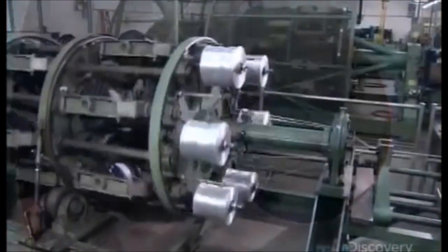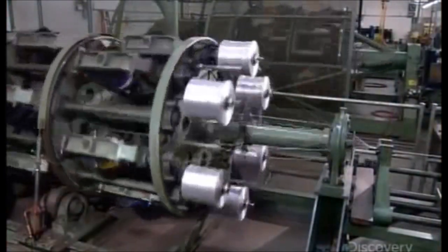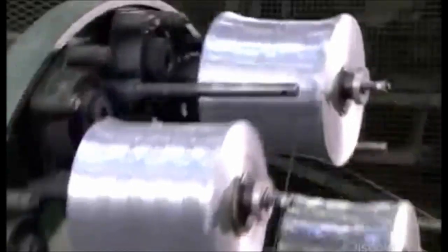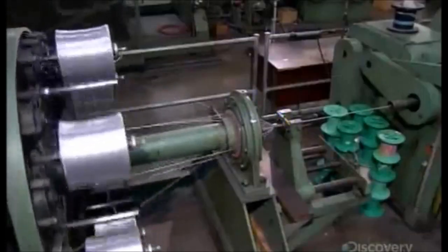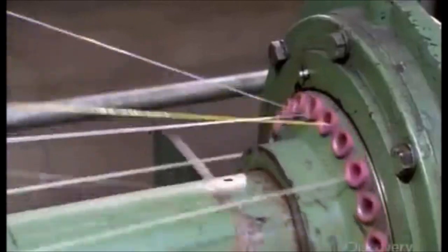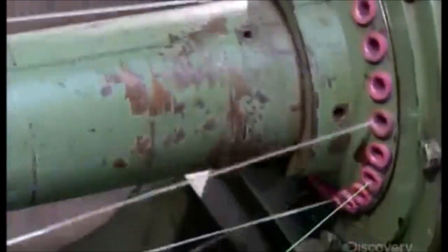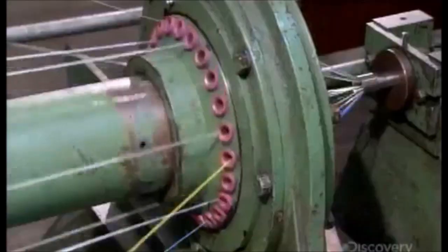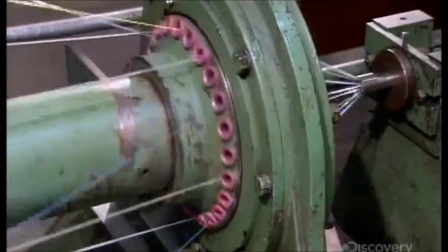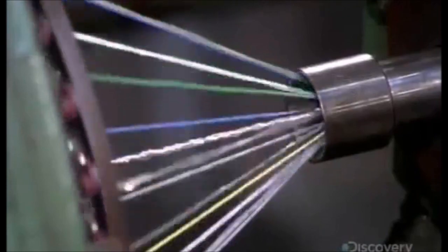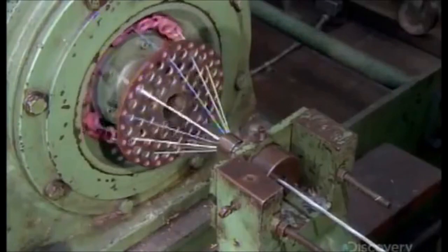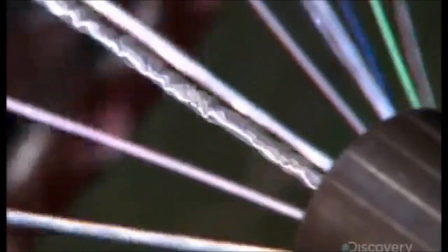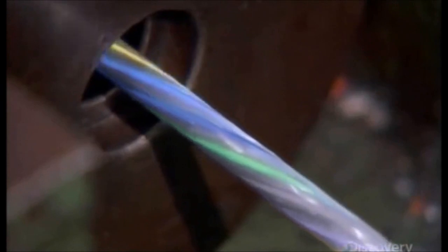At the center of this particular cable is a twisted pair of insulated conductors. Around them go color-coded insulated conductors and fillers to fill in the gaps between the conductors, giving the cable a smooth cylindrical shape. Here, the fillers are strands of polypropylene foam. An orientation plate aligns the components in the proper configuration as they enter the cable assembly die. The components exit the die with the fillers wound around the insulated conductors, which wrap around the central wire.